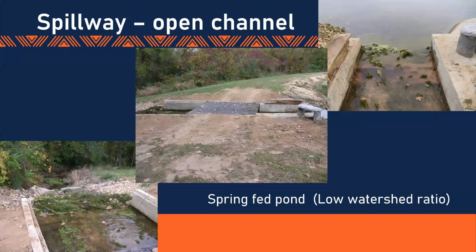One flaw or fault in this one that I see is the barren soil on either side of that spillway. It is actually sunk in just a little bit, so should it get up close to the top of that, or actually over the top of that spillway just a little bit, it really puts that dam in danger. One of the pieces to this, though, is while you see the tracks across it, they had just done some repair work on it and had reseeded, and the grass hadn't taken off and reestablished in that area. So under normal circumstances, it wouldn't be quite that much barren ground around it.